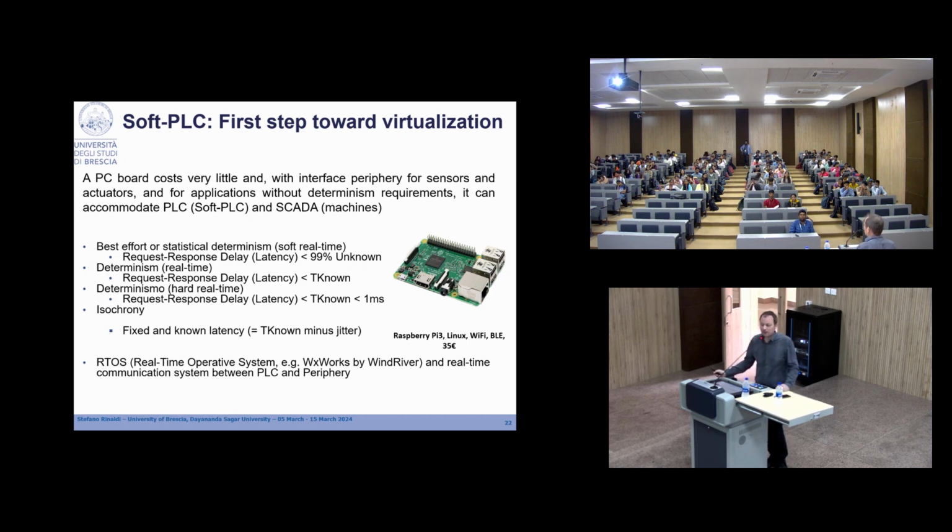The first: a traditional PC platform has a very limited number of digital input and output and analog input and output. Generally, the number of digital inputs and analog inputs on a traditional PC platform is close to zero. So the problem with a soft PLC is that it is not easy to wire sensors directly to this kind of platform. And the other problem is